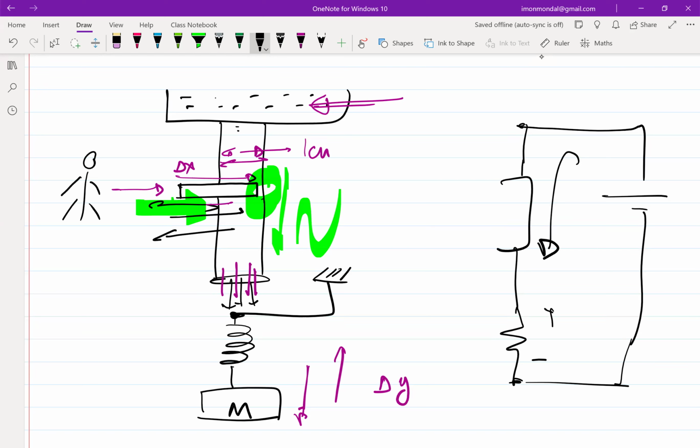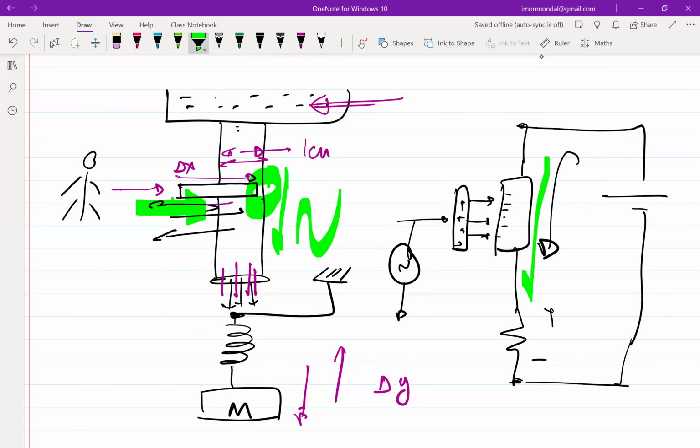Capacitor is one thing that holds charge. Now in order to change the charge of the capacitor, I don't have to change the value of the capacitor per se. I can change just the voltages, which is in my control, right? So if there is a capacitor plate here, I apply, let's say, a changing voltage here, which can change the charge on the other plate. Then I use this modulating charge, and I pass it through in the direction that I want. Then it is arguable that it's possible to make a device which can give us some incremental amplification, voltage amplification. Right? Make sense?